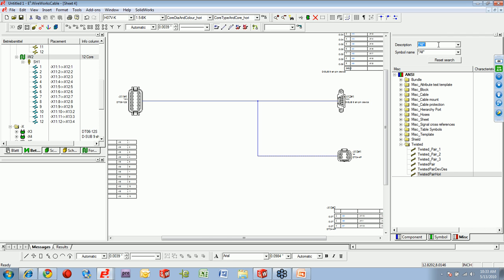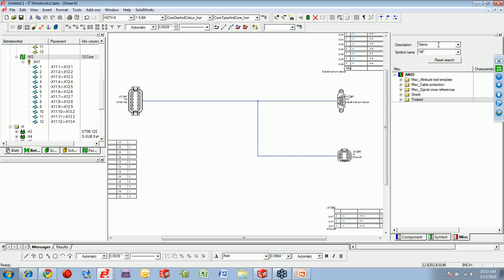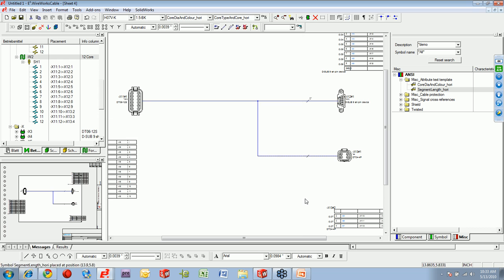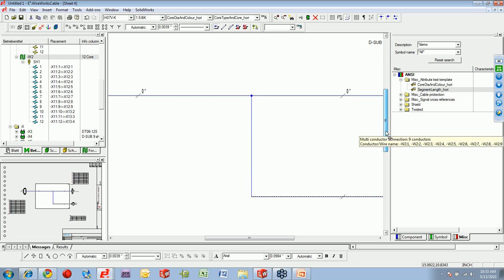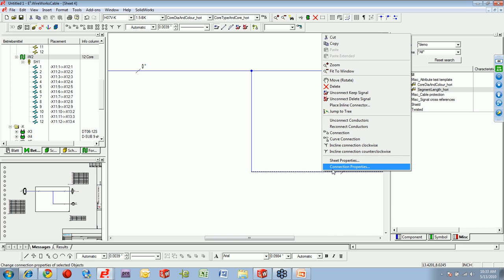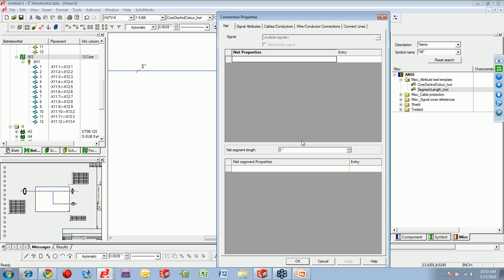Let's filter out my annotations that I use regularly here. So very quick to apply some annotations to those, but so far I don't actually have any length applied. You can see that there's 0 length. Mainly, one part of it is because I haven't associated with SolidWorks yet. The goal is to get some of these lengths coming from SolidWorks, but I can, within E3 itself, just go and apply a length myself.